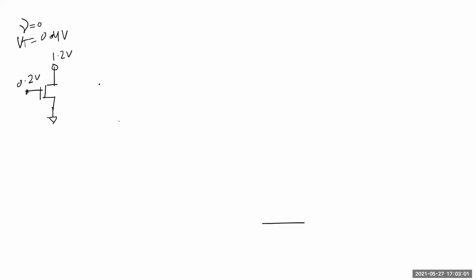In saturation, at the drain end it should get a tapered channel, so at the drain end it comes towards the source and it will not be a gradual channel approximation anymore. That's correct. Yeah, the channel charge pinches off there.